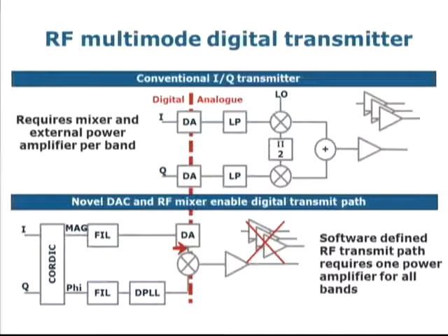And having said this, it is possible to remove, for example, driver stages for different frequencies, power amplifiers for different frequencies, and we know it is up to 5 in today's 3G handset, down to 1 only. This is good, saves cost, that saves power consumption, and of course, it saves space.